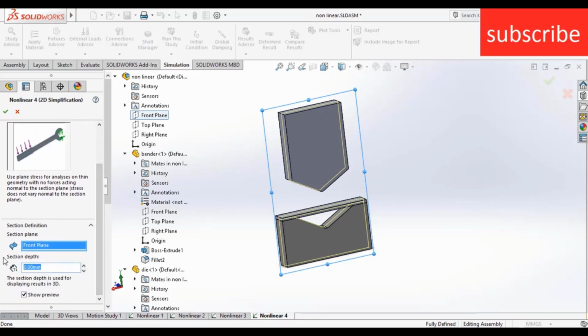Now enter the section depth of 50 mm. A question will arise in your mind: why is the section depth 50 mm? Because the total width is 50 mm and this is the symmetry of 50 mm. If I type the value of 20 mm, when I do the simulation and want to see the result in 3D, I can't see the result in 3D properly, because I selected a width of 20 mm, but in reality the total width is 50 mm.